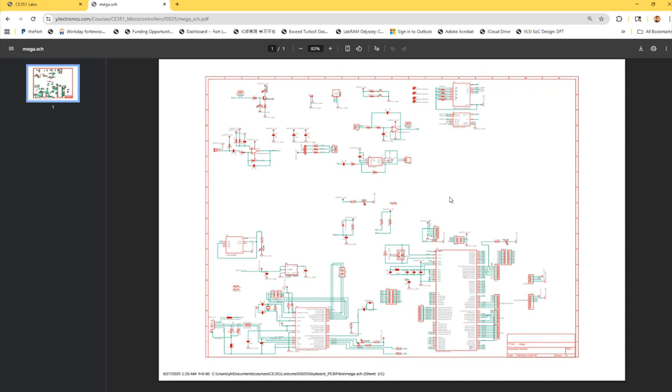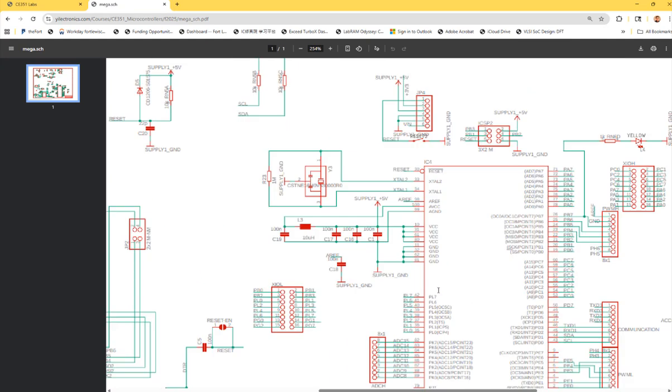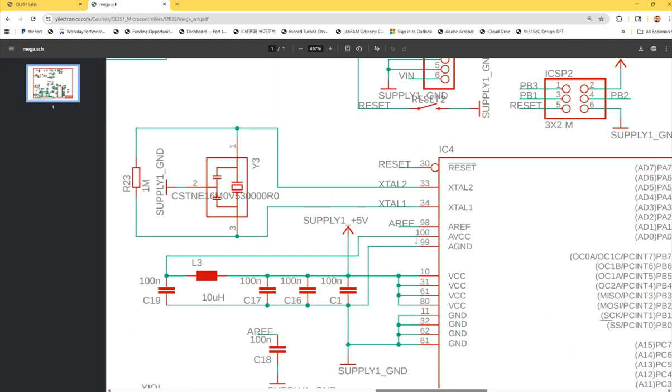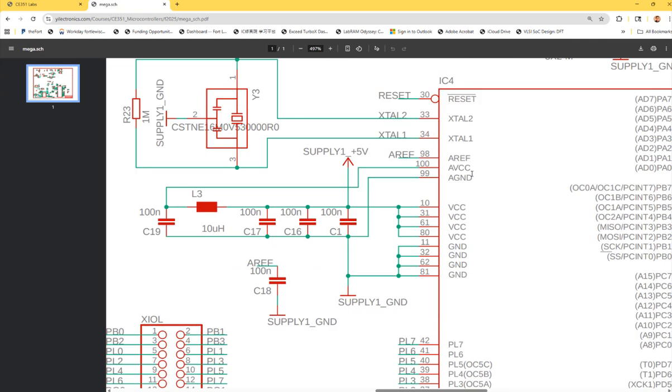Okay. So if you look at the microcontroller over here, first, as we have learned, usually we set up a reference voltage for the ADC or DAC, and that defines the range, and then we divide it by how many bits of resolution or how many steps are in there, depending on the resolution of the ADC. So what's the resolution of this ADC? 10 bits. You should only answer 10 bits.